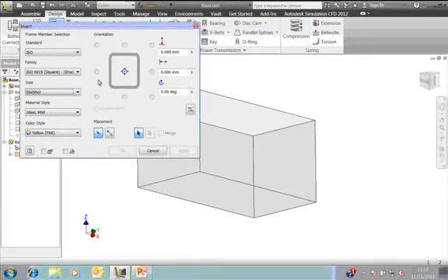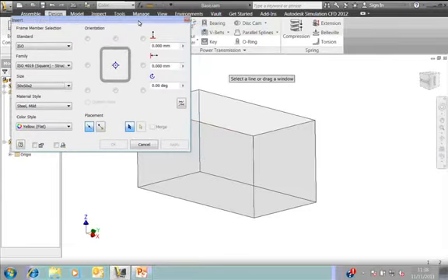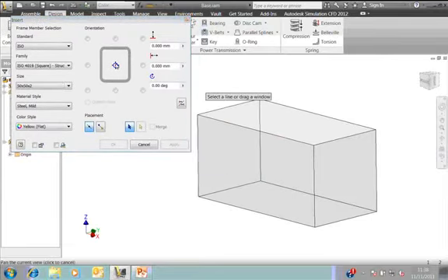The dartboard effect here enables you to align either a corner, the centre, or the middle of a face with an edge that we're about to select on the skeleton model. I'm just going to, for the ease of presentation today, just use the centre. We can then jog it backwards and forwards, and also rotate it and mirror the steel section as well. So for C profiles and so on, this will be useful.